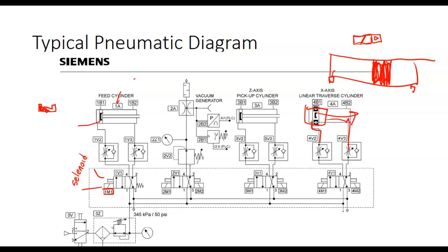And the biggest advantage of a rodless cylinder is the stroke. You can have these long strokes. Every one of the gantry cranes on the right is a rodless cylinder. We've got two on the Festo line. They could have done the lift with a regular cylinder because it's only got probably a 9-10 inch stroke. But both those other robots have big old long strokes on them, and you're trying to stick a rod out that long, right? You understand?